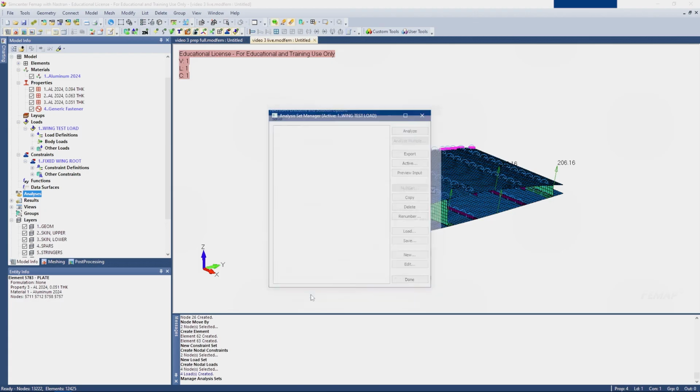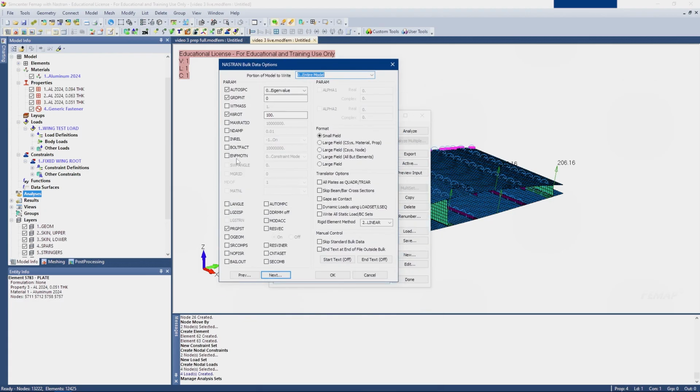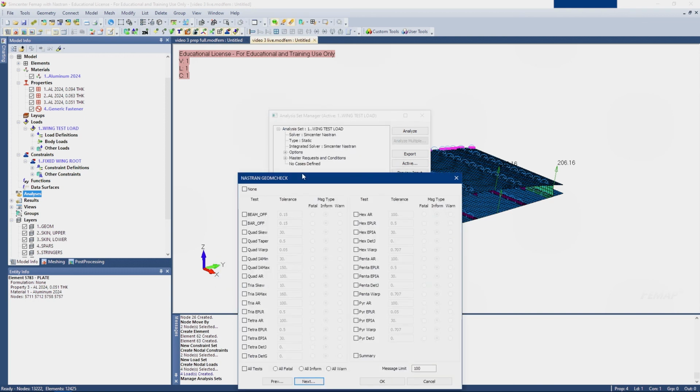This content you can leave unchanged. These are some settings, like if you're doing acceleration, sometimes you want to check weight mass. These are a few other settings like large angle, large displacement, if your stiffness changes drastically based on the deflected shape. But in general, the defaults are going to work.